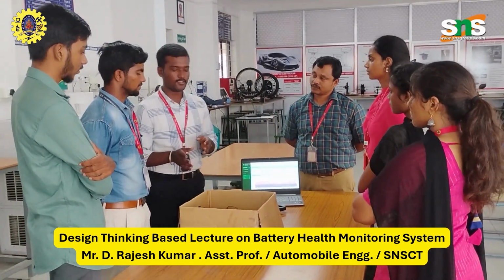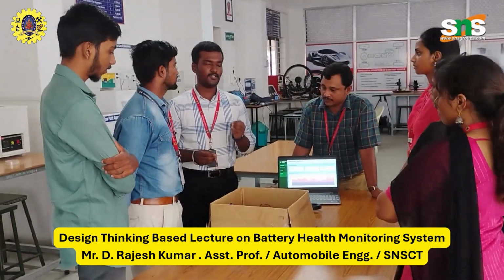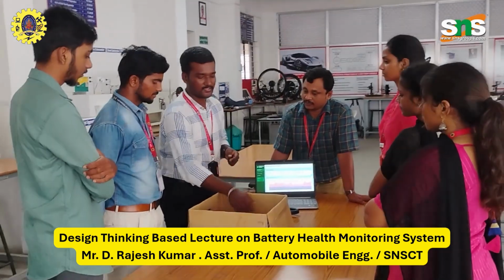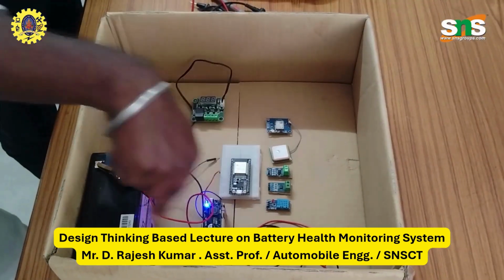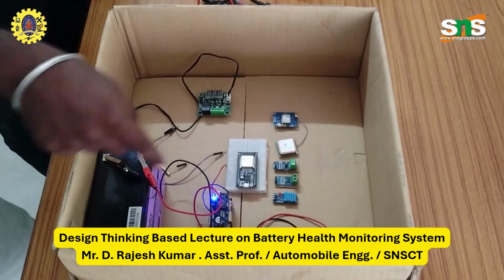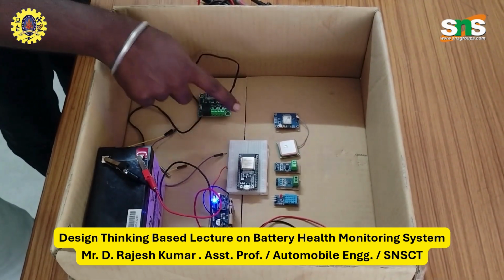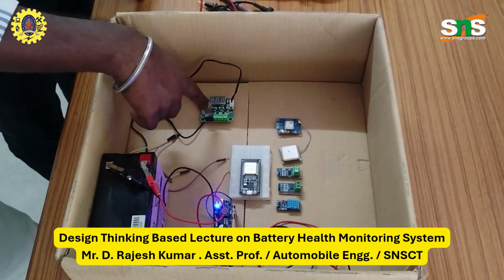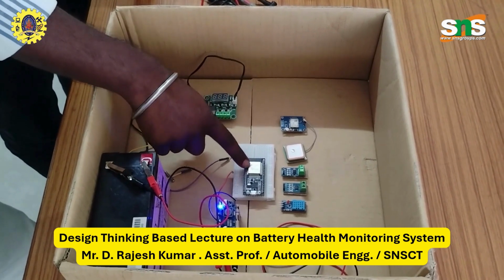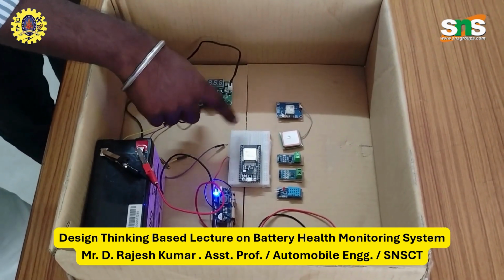We have used a lead acid battery, a 12-volt battery, to get the data of current and voltage, and we use a DHT11 for total system temperature observing, a current sensor, and a voltage buck converter for stepping down the voltage, a GPS module for tracking the vehicle, an advanced current sensor which comes with an LCD, and an ESP32 module which acts as the microcontroller in this system.